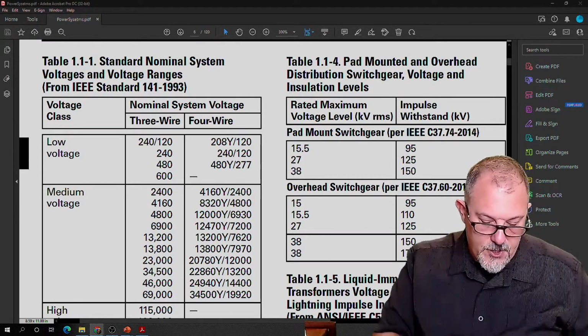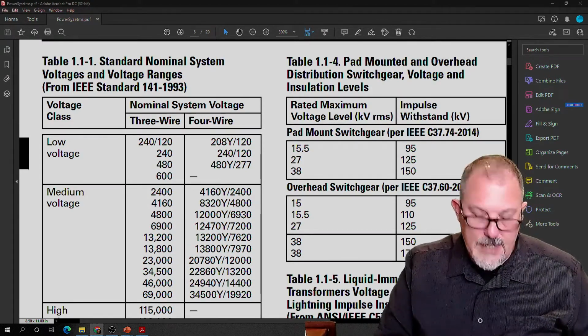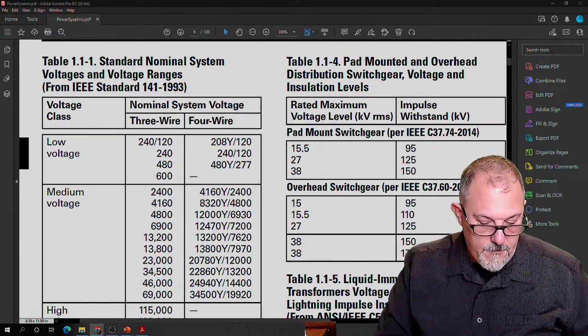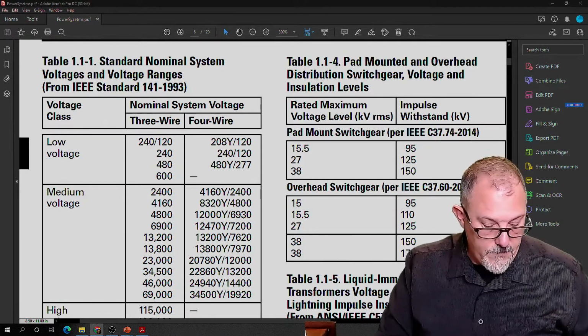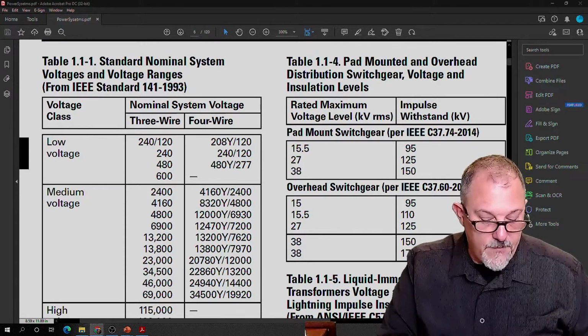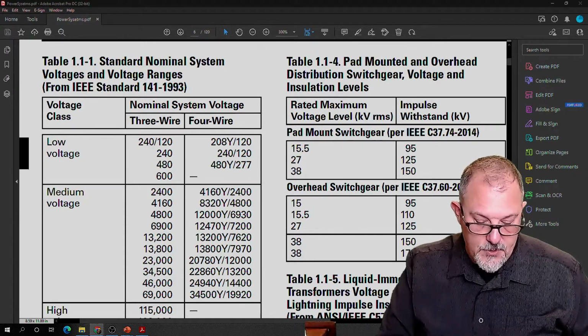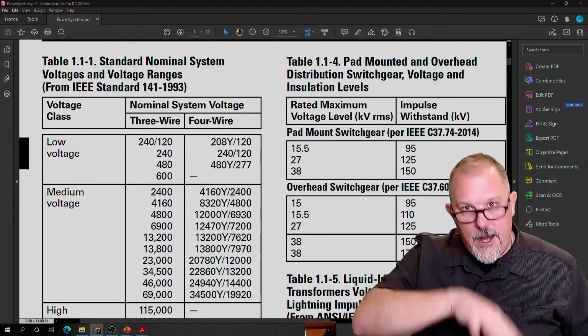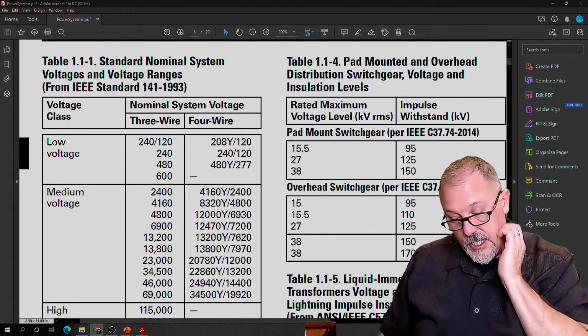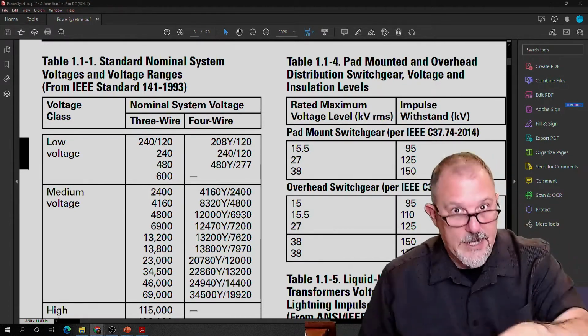My starting currents will decrease by 10 to 12%. And they're a function of voltage. Maximum overload capacity, voltage squared, I'll decrease by 19%. And then it's the opposite effect if I have over voltages. So voltage selection